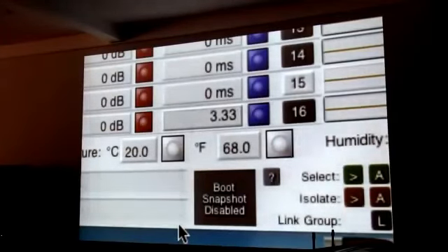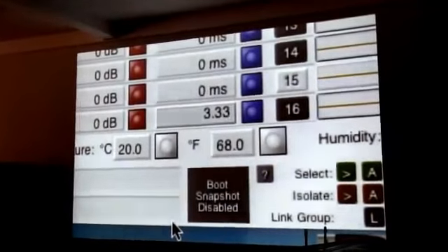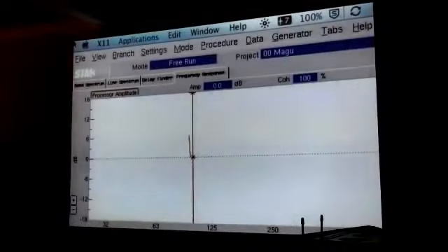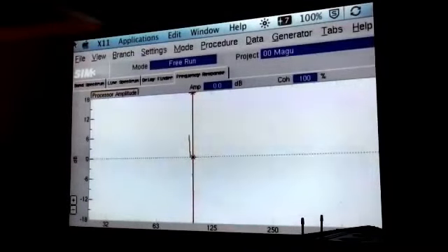If I do 3.33 milliseconds, how much is this for the time period of 100 Hz? 120 degrees, or 1/3 of the time period. In this condition, the summation of two audio signals is 0 decibels. So if I mute one of the signals, the level is still 0 decibels. I unmute, the level is still 0 decibels.